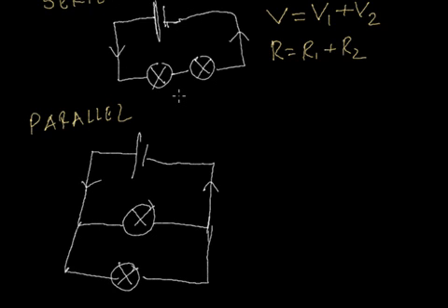Rather, they're connected in parallel. You will see two or three lines in parallel, meaning if one of the lights doesn't work, current will flow through the other. A complete loop is working, and the circuit is not broken. That's why parallel connection is preferred in this type of activity.